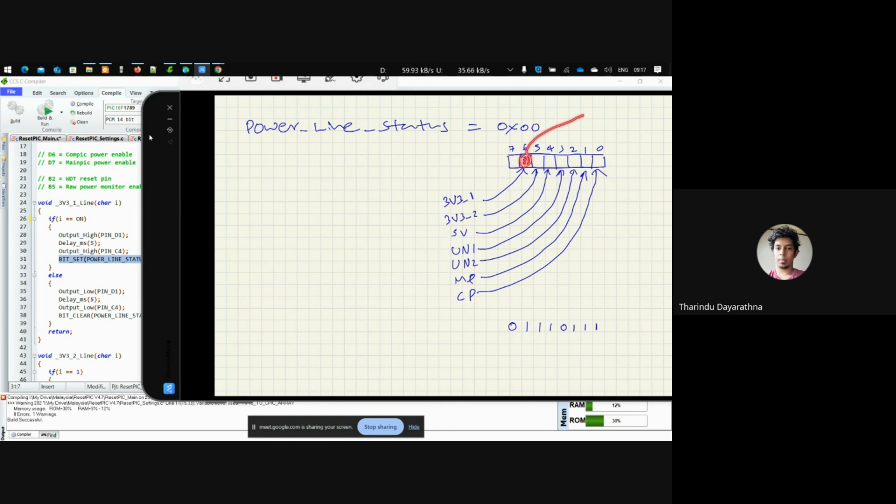It happened because one enable line was short circuited to high, so the 3.3 line was on even though the reset pic did not turn it on. So we could find the problem like that.